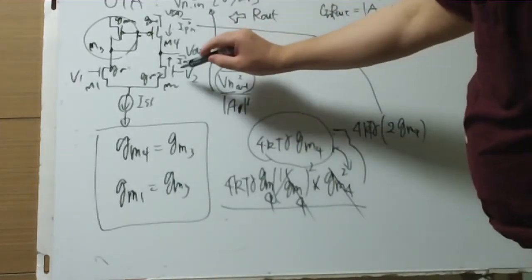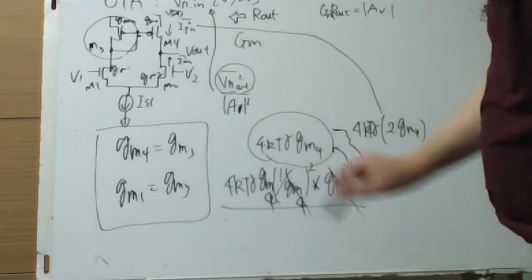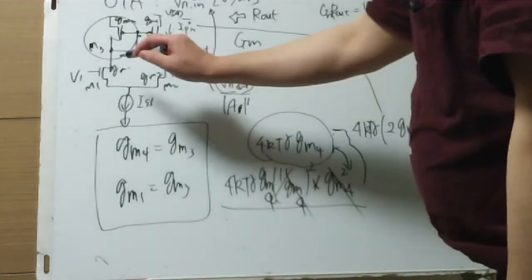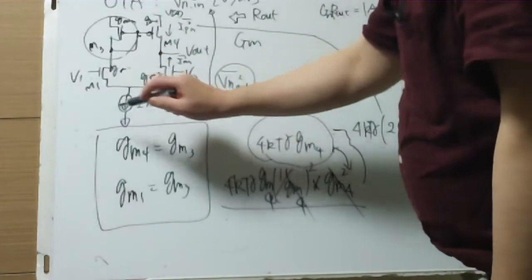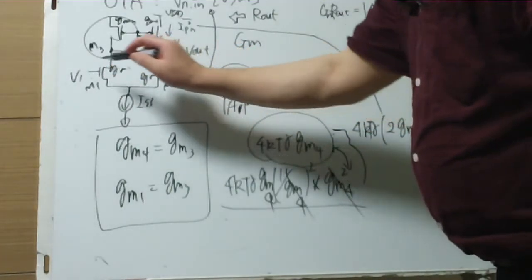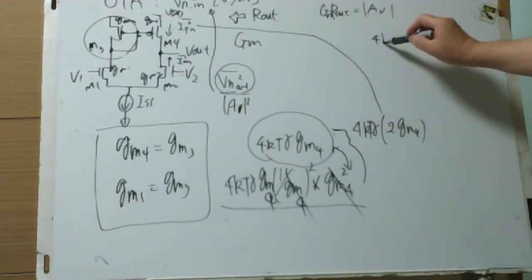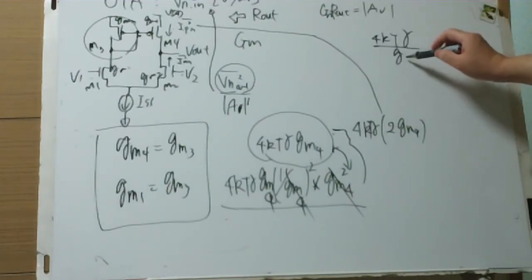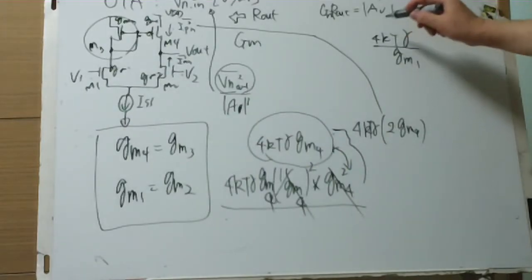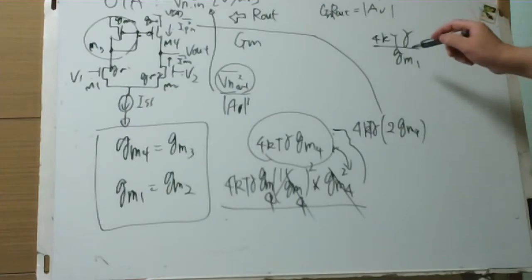And for the other side, the NMOS, what is IN squared bar? Input referred, for the lemma we know from the Razavi textbook: gate input referred voltage noise from current noise is 4kT gamma over GM1 or GM2. GM1 equals GM2, so this is 2. This voltage is input noise, gate referenced noise, gate referenced current noise, gate noise